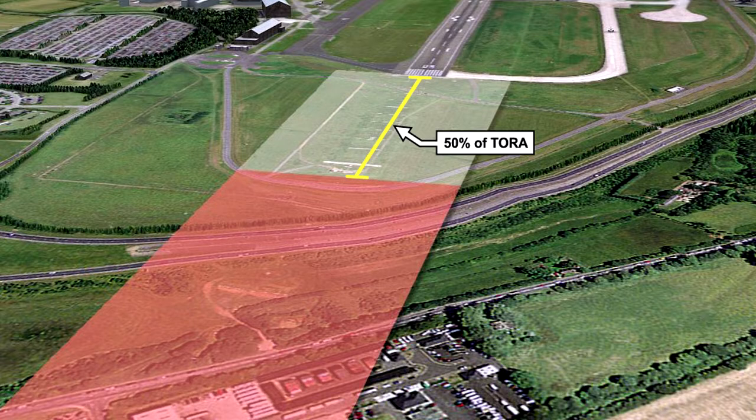To summarize, a clearway is designed to be an area free from objects which may cause hazard to an aeroplane in the initial phase of flight, particularly in emergency situations. The clearway serves no other purpose and therefore may not be used as an extension to the landing area or stopping area.